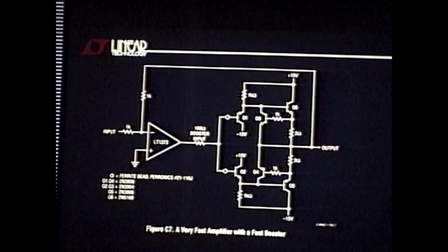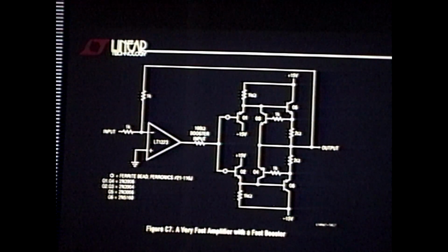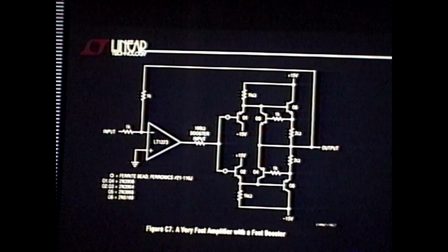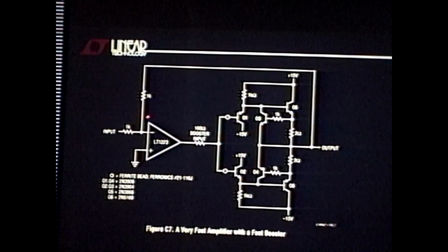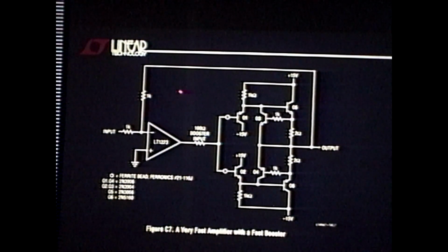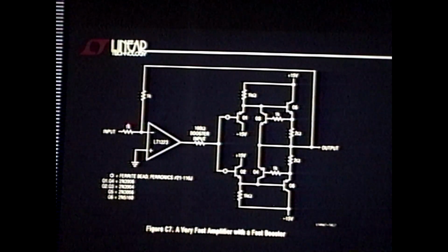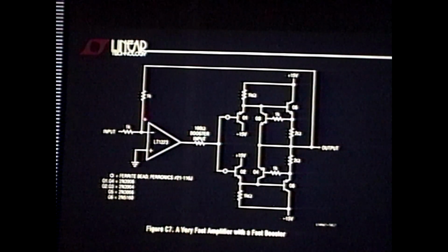And you notice again, in accordance with the preaching I did in the first lecture, I don't use a feedback capacitor to stop the thing from oscillating. I stop it from oscillating by killing the gain bandwidth in the circuit. I might use a feedback cap here to trim overshoot, but I want to kill the gain bandwidth. There is where the cap should go.